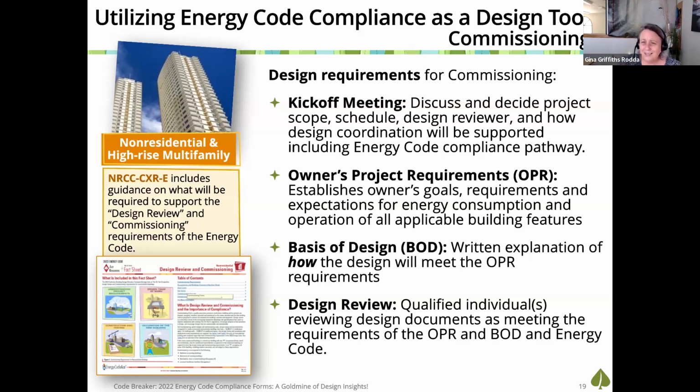We can always exceed the code, especially when it makes sense for the project goals. We're going to have a kickoff meeting. Does everyone know what we're doing? Does everyone know where we're building? Are there any REACH codes, local ordinances, zero net carbon design goals, LEED, et cetera, that we need to be aware of and that need to be incorporated into the design process? What are the owner's project requirements? What do they want? What's the basis of design? This is the most important document to me,